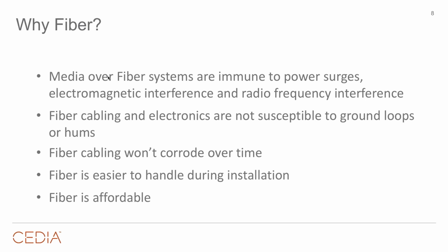That means that fiber can go into these installations where we have different ground potential issues, where we have heavy lightning, in the southern part of the United States, the Southeast, places like South Africa, right, where there's lightning activity. Fiber's immune to that. Places out west where it's really dry and there's a concern over static electricity, fiber's immune to that. Major advantages of using a fiber optic infrastructure is the devices have immunity on each end from electrical issues. And then the other major advantage here is there is no bleed over.